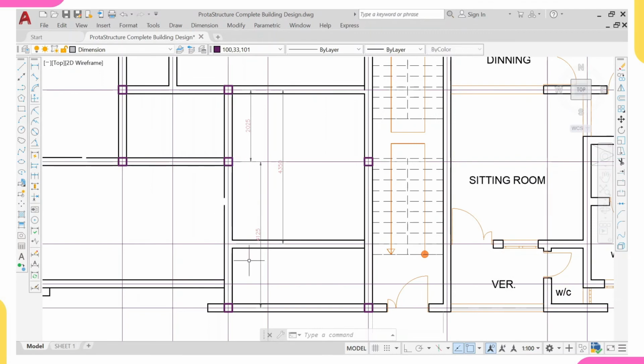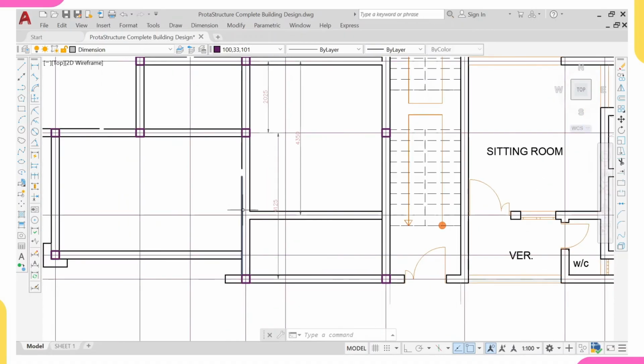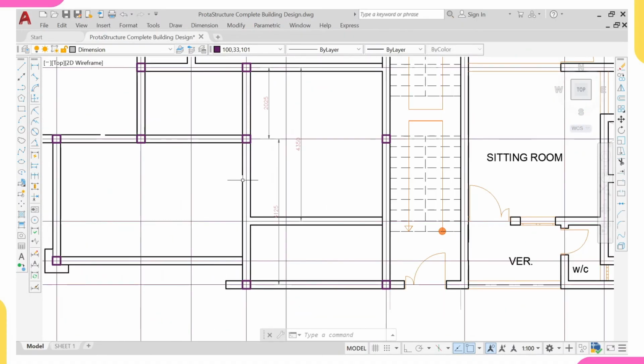You know that this beam now is 4.125, but this beam now is carrying 2-point load. Two, not just one. That's the load from this beam and also the load from this beam. So the slab load is transferred to this beam. Then this beam will divide it into two. It transfers some to this column and then transfers some to this beam.